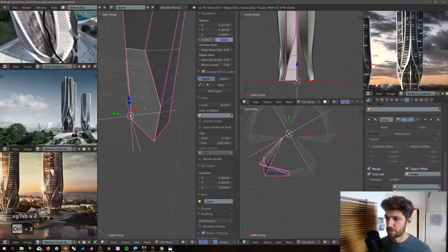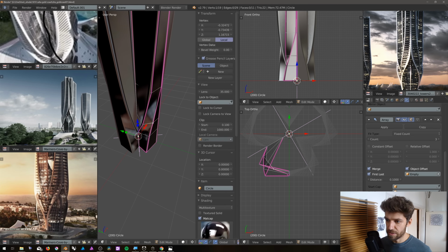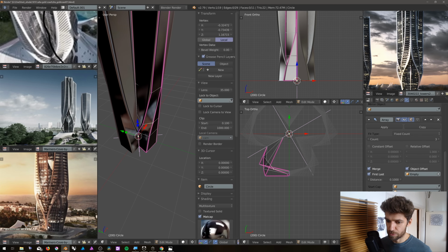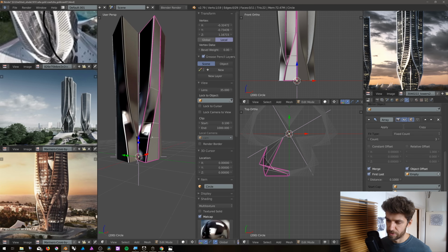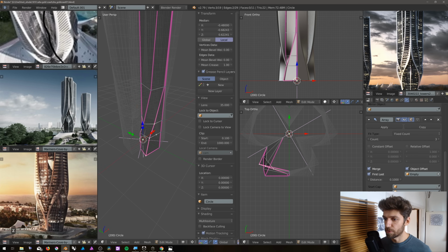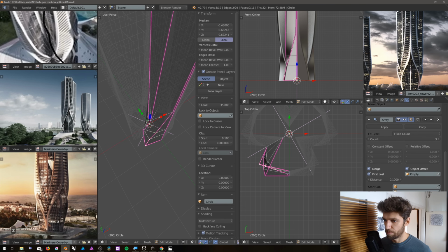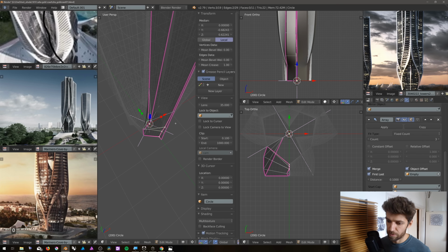I'm going to get rid of this face. Is that right? Nope. X face. So this line, that vertex, it needs to squeeze all the way up to that corner as well. Everything is converging to that corner. So I'm going to do a similar thing with this. Let's push this to 0. Scale it on, what did I scale it on?